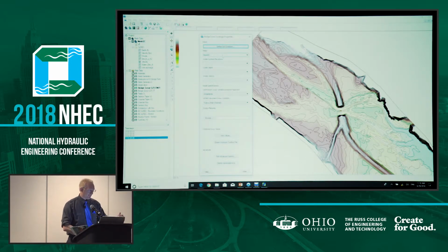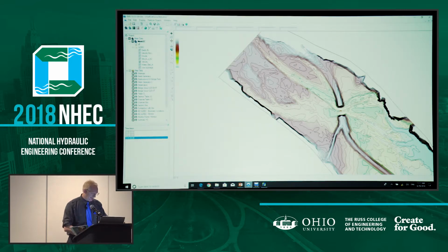And then we're going to select our mesh. This is coming from our data there on the left, just this mesh data set. And you can select which mesh if you have multiple meshes. And I'm going to select the data sets for water surface elevation, data set for water depth, and then one for velocity. These other options I'm going to come back to in a minute. So I'm going to close this dialog, and now I'm going to create our arcs.